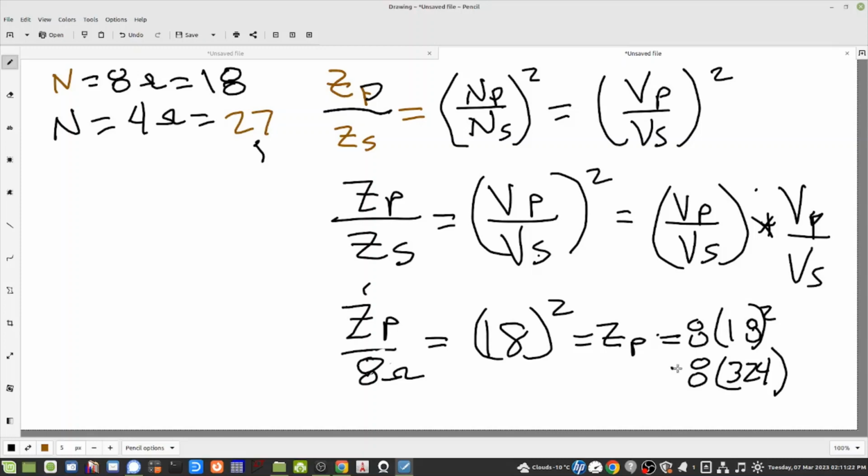So that says ZP equals 2592 ohms. Well, that seems reasonable, because the transformer should be around 2500 ohms for 2 tubes in parallel. For an 8 ohm load, for a load impedance of a single tube being 5,000 ohms.